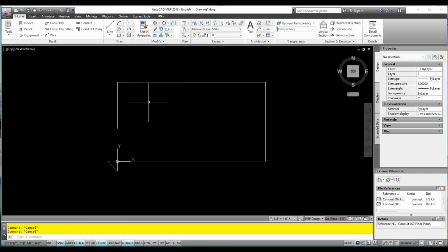Oh, my mistake. I forgot to click on the screen. Let's do it again. REC, enter. Click that, pull it out. Type in D, enter. We want 24 by 6 inches deep. Enter. And I forgot. You're supposed to click on the screen first, then hit escape, escape, escape.